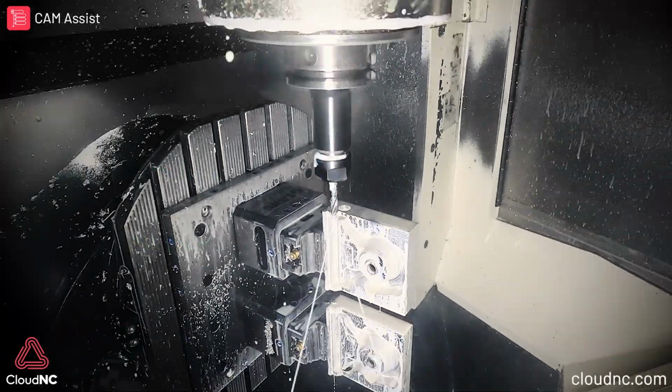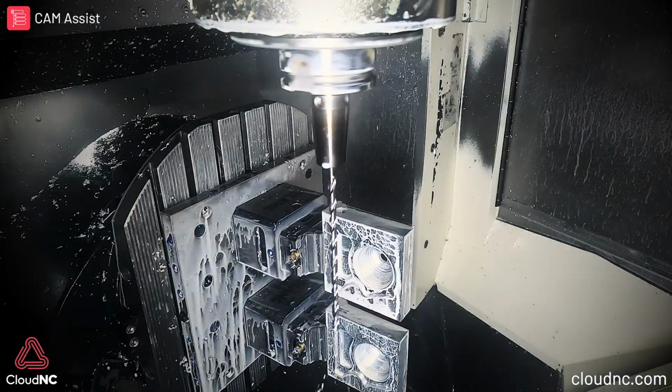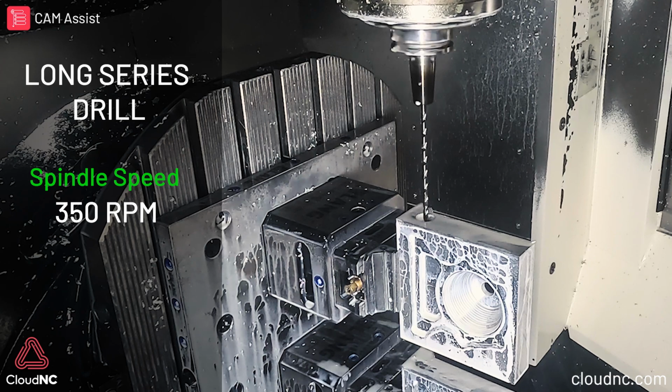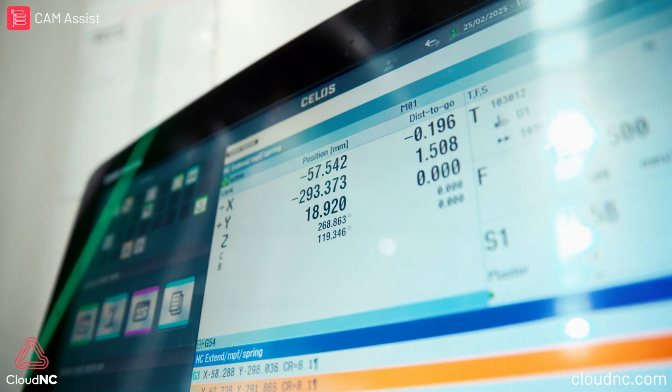With the pilot hole in place, it is now time to bring out the long series drill. Due to the excessive length of this tool, the speed must remain under 500 RPM until the tip of the drill is submerged and into the pilot hole, as centrifugal force would cause the drill to break if it spins up to full RPM without the support of the pilot hole.